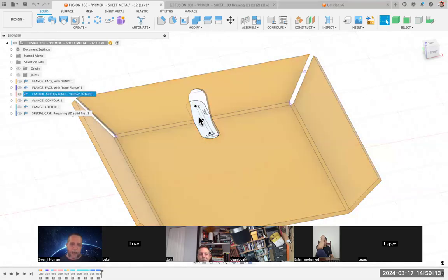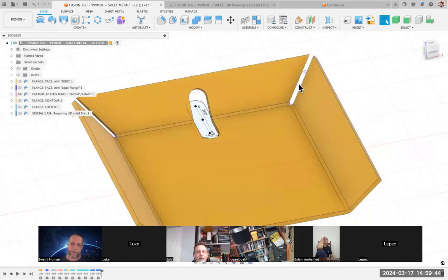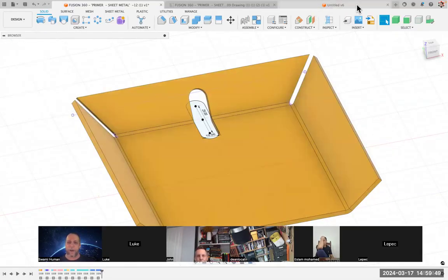We are going to make this slot across this bend, but we have to unfold it so that those cuts go perpendicular to the face of our sheet. Because when we take our laser cutter, plasma cutter, whatever we're going to do, we can only make a straight cut downward. So if we made our slot in this configuration, we would not have that situation. We'd have our cuts going at an angle because of this being mitered. So we're also going to look at this mitering here. All right, so that's what we're up to. That's where we're going. And here we go.